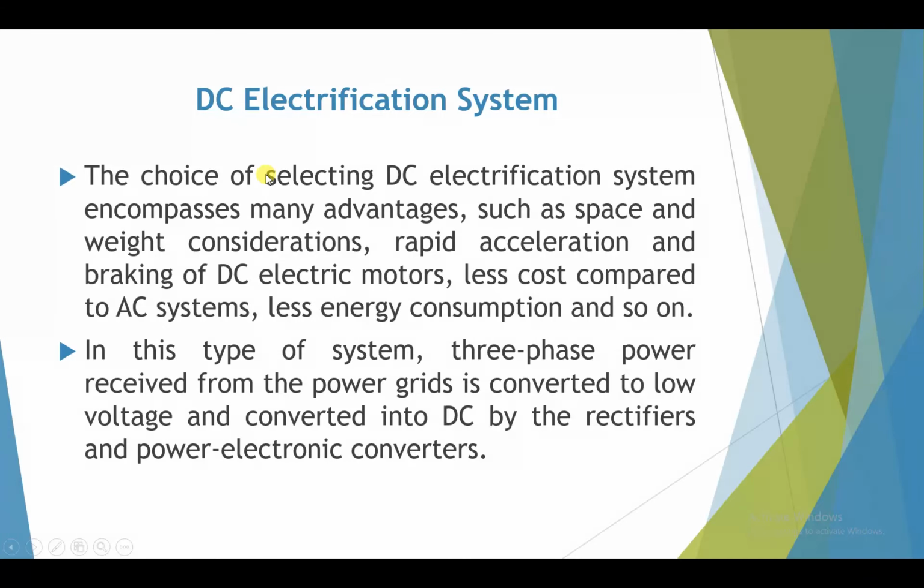The choice of selecting the DC electrification system has many advantages, such as space and weight consideration, rapid acceleration and braking of DC electric motors, less cost compared to AC system, less energy consumption, and so on. Those are its advantages when we use the DC system.